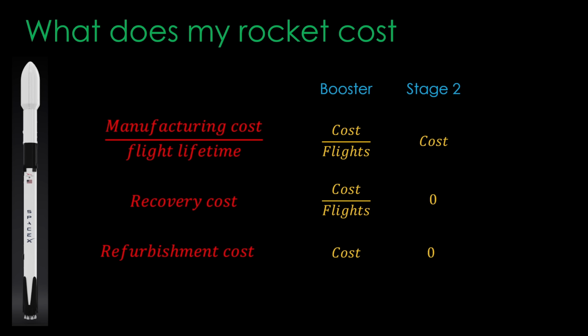Assuming that you build a rocket with low refurbishment costs, the big drivers for the overall cost are the recovery cost and the cost of the second stage. If we want to optimize our system for low prices, those are the 2 big levers we can use, with the second stage probably being more important as it is less dependent on flight rate.